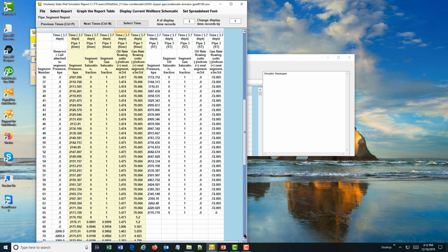So the condensate rate is not significant, and we're essentially recycling gas. We are pumping a lot of gas in, but we're simply recycling the gas because the gas condensate well does not require a lot of gas to circulate, to lift. So let's look at the case where we have used the rate of 20 instead of 100 for the gas lift rate. So here we see that the rate is about 3.5.